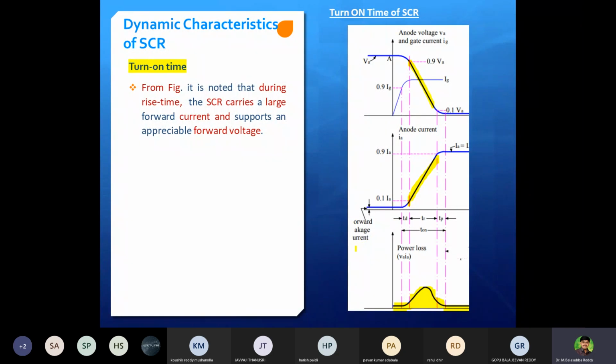So whatever I shade now, during that instant the device is changing from off state to on state, during which the time interval is 1 to 4 microseconds. Within that duration, a near maximum voltage is present, and maximum current is also present.